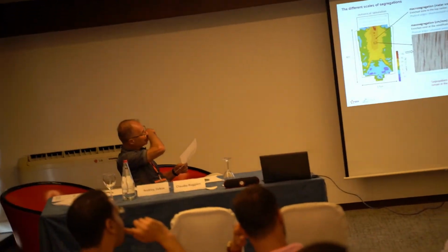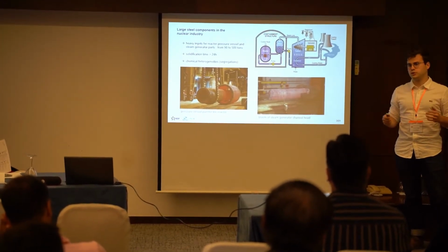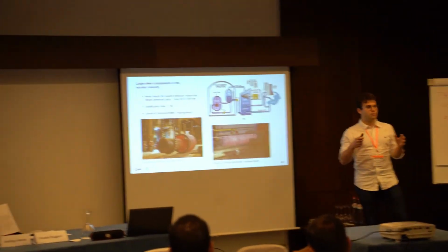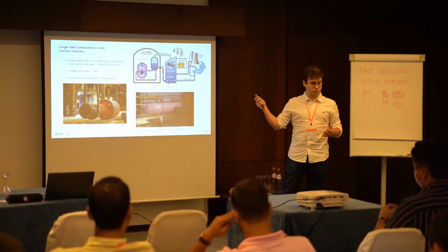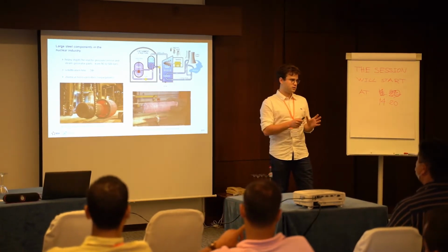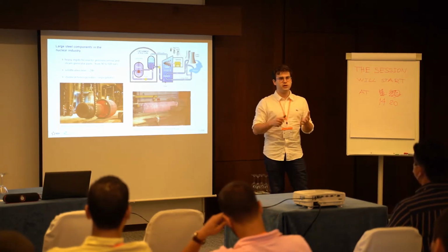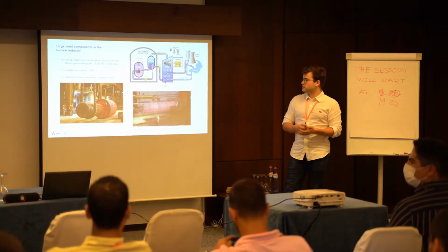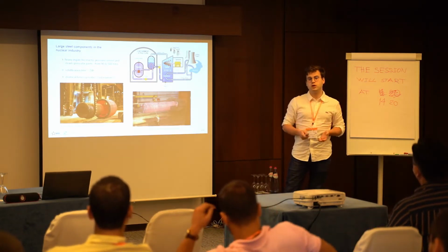So for the context, in the nuclear industry, some components such as reactor pressure vessel parts or steam generator parts are manufactured from very heavy ingots, from 90 to 500 tons. As you can expect, the solidification time of such ingots is very long, thus allowing the diffusion and moving of matter inside the material. Because of this process, the ingot and then the final product contain significant chemical heterogeneities.